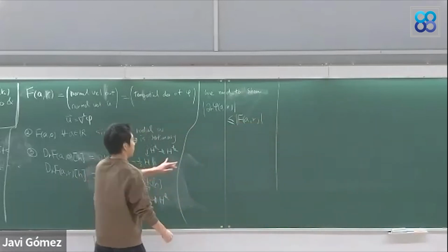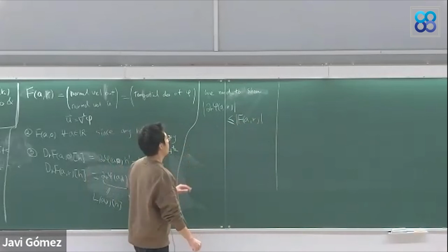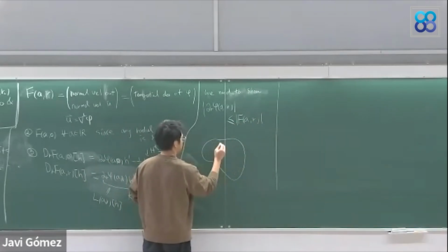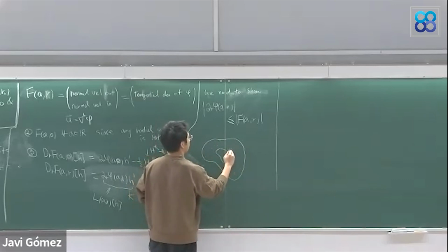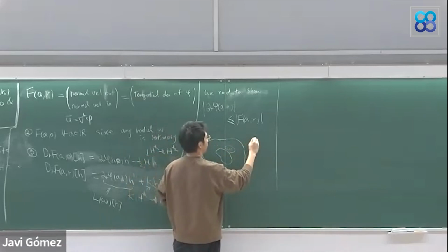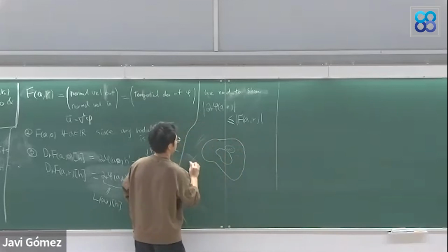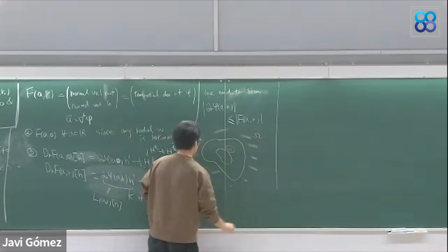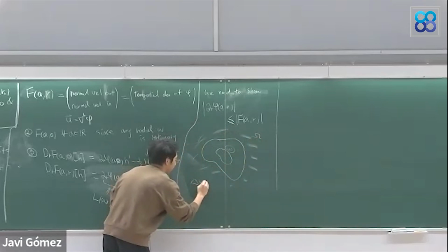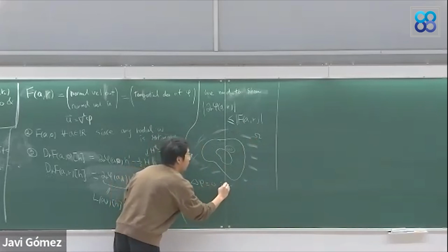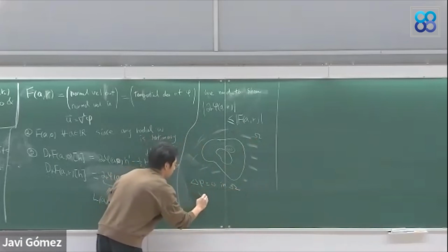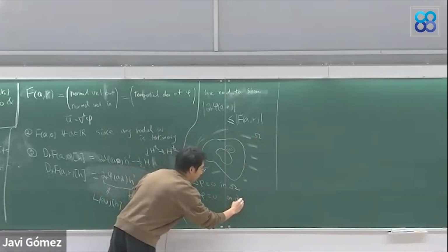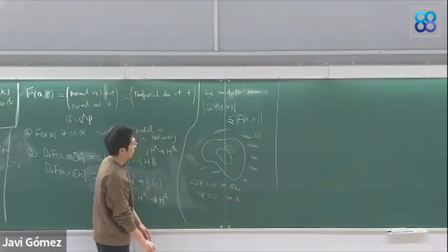This is basically the Dirichlet to Neumann operator bound, because we know that the stream function, this is our omega, and then let's call this exterior domain omega. Then we saw that the Laplacian of the stream function is 0 in this exterior domain, and psi is 0 on the boundary.